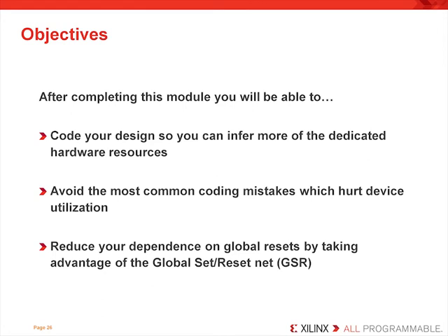After completing this module, you'll be able to code your design so that you can infer more of the dedicated hardware resources. You also will be able to avoid the most common coding mistakes which will hurt device utilization. And finally, you'll be able to reduce your dependence on global resets by taking advantage of the Global Set Reset Net, commonly called the GSR.